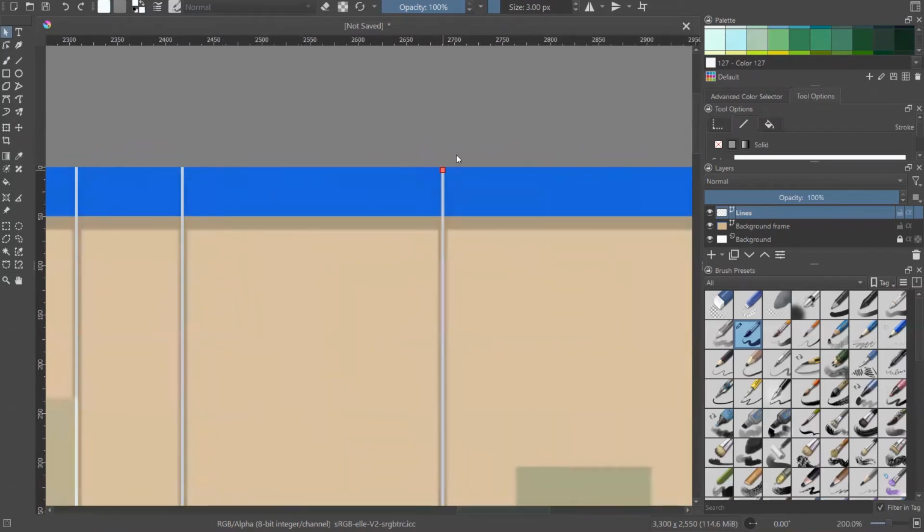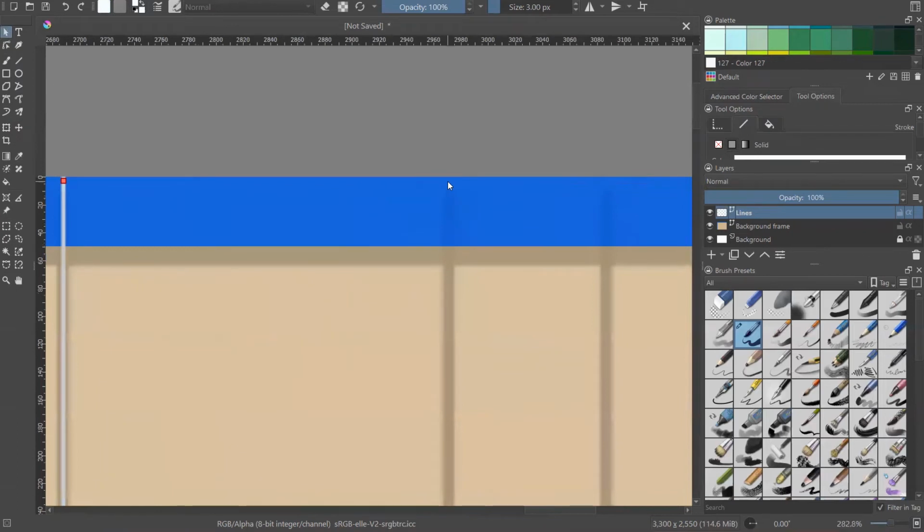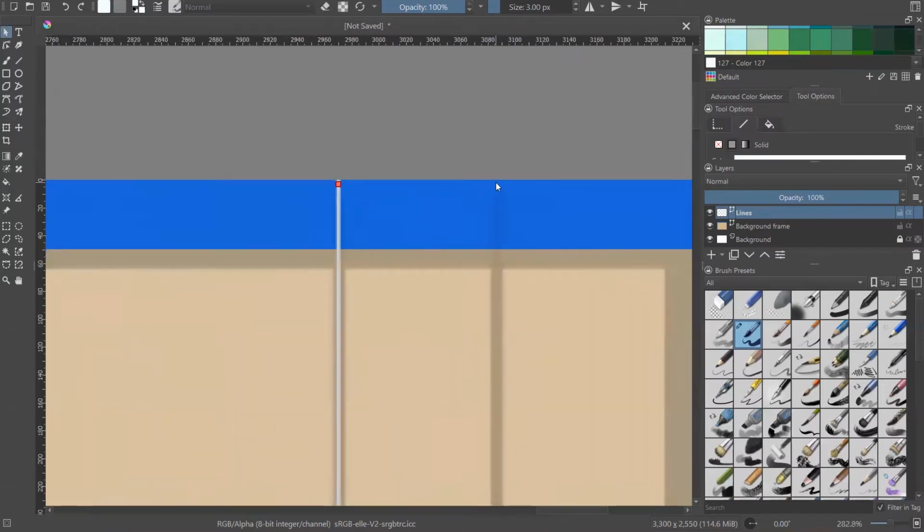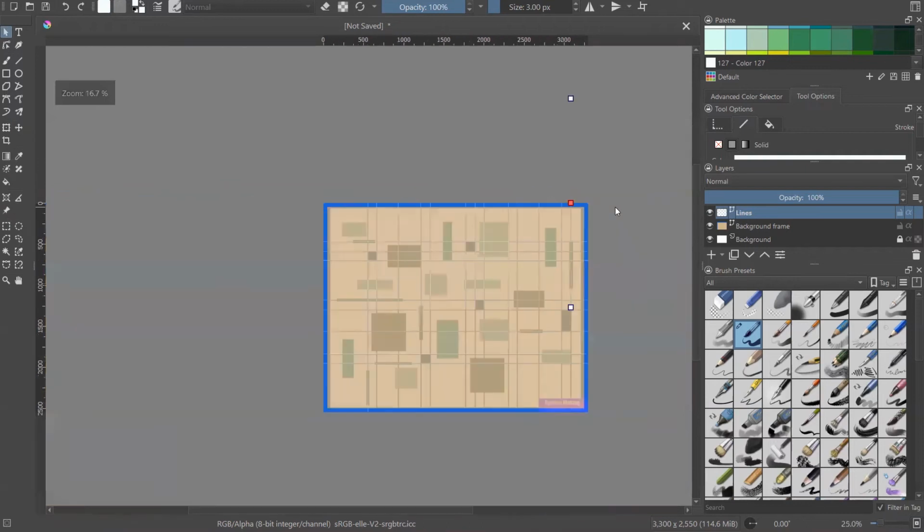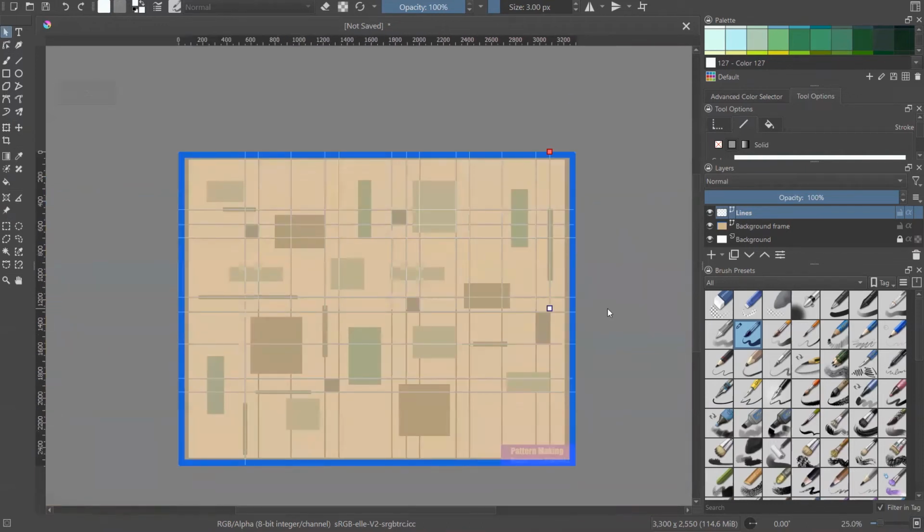Ctrl Alt V. And when I say Ctrl Alt V, I mean Ctrl plus Alt plus V. So this is a 3-button command. Control first, then press Alt while holding Control and press V all at the same time. And that's how we paste in place, at the position of your cursor. So now my lines are in both vertically and horizontally.